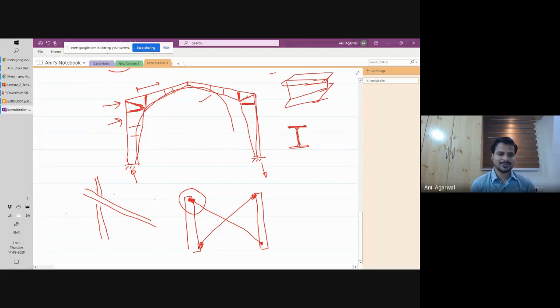My drawing is getting worse and worse. So basically what you do is you have some kind of a thread in this brace, and then you put some kind of an anchor or some kind of a bearing, and then you put a nut here, and then the nut is tightened so that this rod undergoes tension. So then you can maintain tension throughout the loading, right?